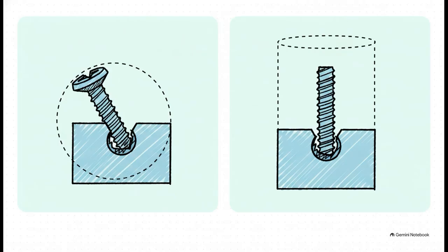If you just shouted projected tolerance zone at your screen, you absolutely nailed it. Exactly like we covered way back in Lesson 4. A standard position callout just isn't enough here. The thing is, a fixed fastener, like a stud or a screw, is entirely governed by the orientation of the produced threaded hole. If that hole goes in at an angle, the extended portion of the fastener acts exactly like a lever arm, multiplying that angular error as it goes up.